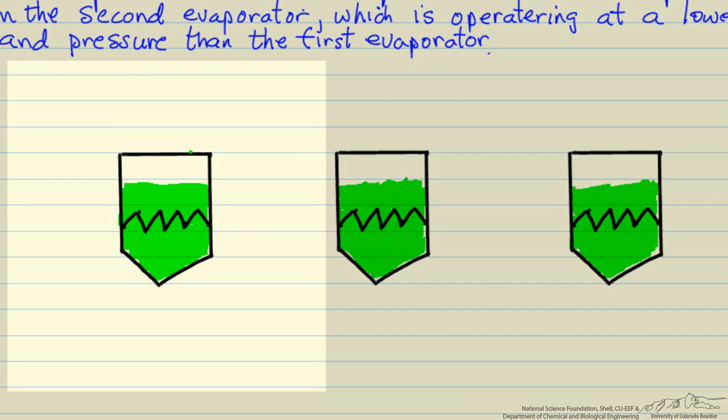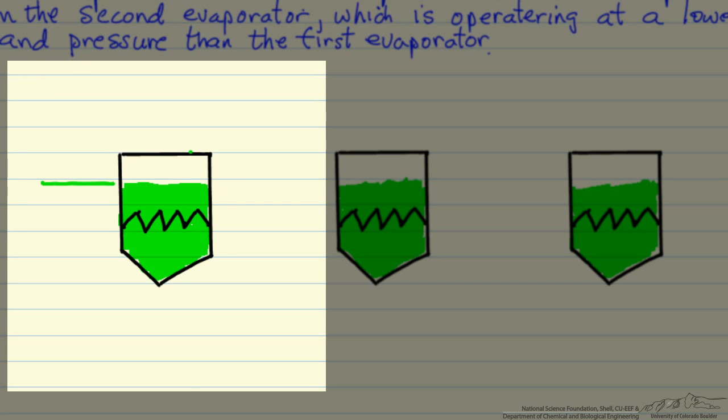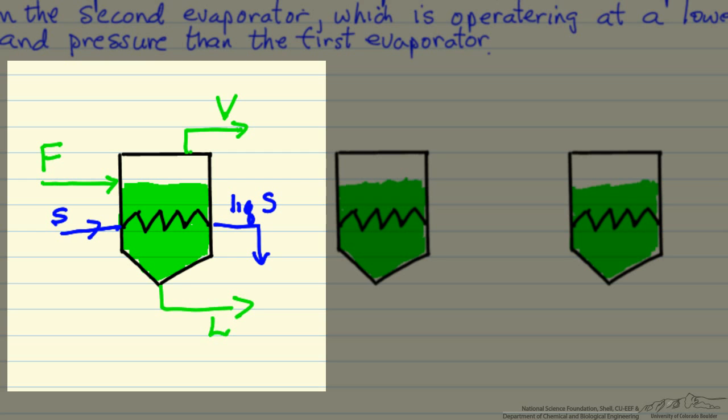So in a triple effect, in the first effect, we're going to have a feed coming in. This is a liquid at low concentration of solute. We're going to vaporize some fraction of this, and then we're going to create a more concentrated solution of liquids. We carry out this evaporation by having steam fed to these heat transfer coils, and then we have liquid leaving. We're assuming the feed is at saturation pressure. We condense and drip out the liquid also at saturation temperature and pressure.